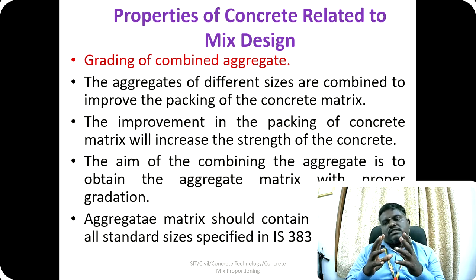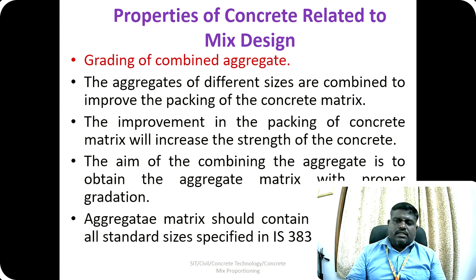So there are two types of gradation. One is poorly graded and another one is well graded or properly graded aggregates. If we use properly graded or well graded aggregates, then it will have fewer voids, and due to that the particle density of the matrix will be good, and it will have higher compressive strength.